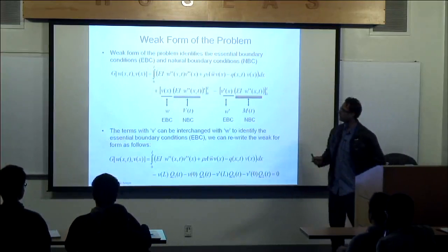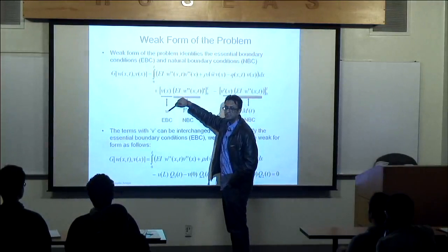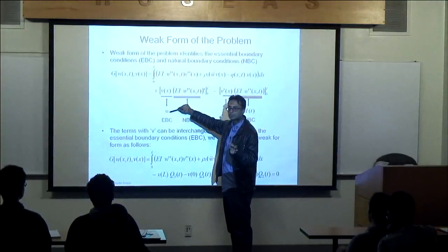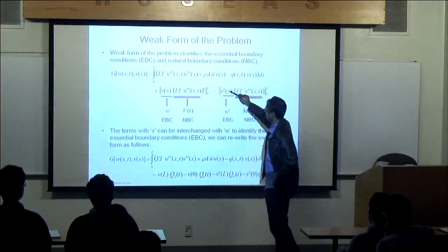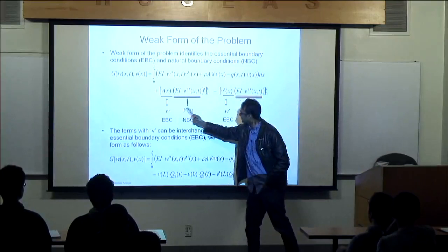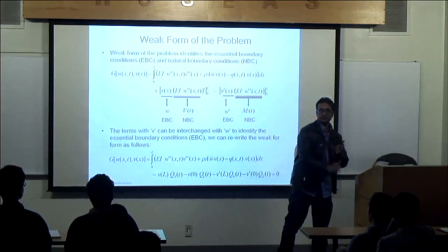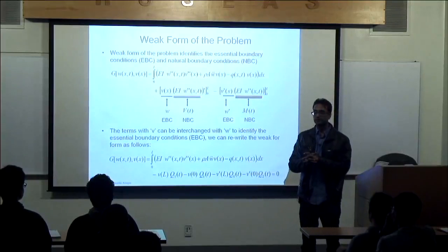So we've discovered that this is the essential boundary condition. We know that W is, anything specifying W is your essential boundary condition because V shows up here. And then there's a V prime here that tells us that W prime must be an essential boundary condition. This also tells us what variables must be continuous across element boundaries. Okay, I'll start introducing some terms like conforming element.